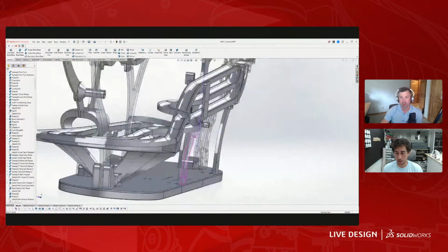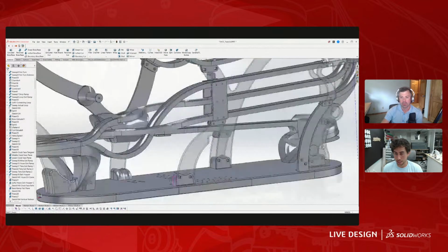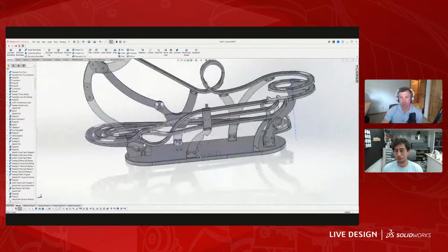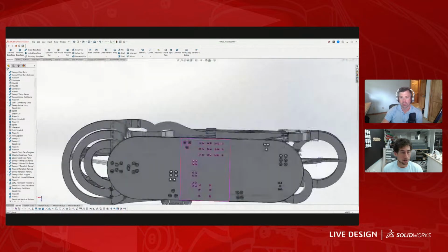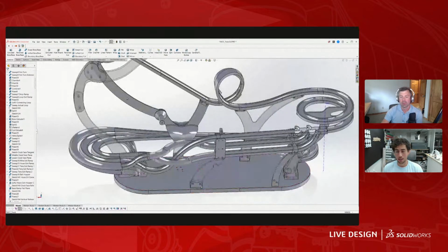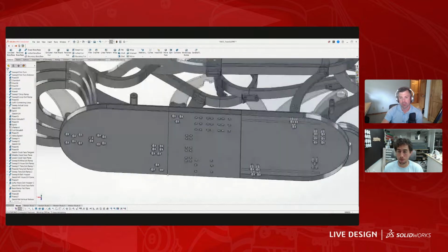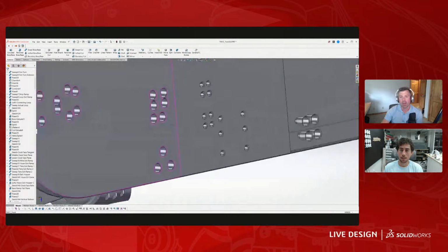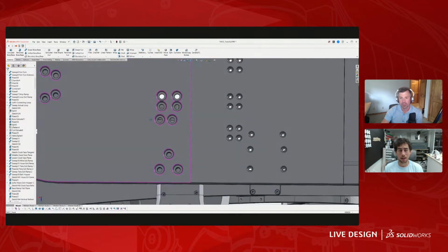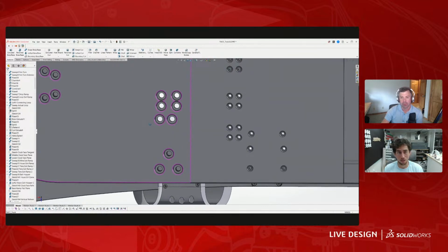There's a lot of parts here that aren't showing, but you can see brackets like this, where it's all screwed into the bottom of the base. This base I ended up having to make in 3 parts so it could fit on my 3D printer, and then I laser cut a top panel. The reason I 3D printed and laser cut is because when you 3D print, you can recess countersunk screws. If I was laser cutting, I'd have to countersink all this stuff after the fact.